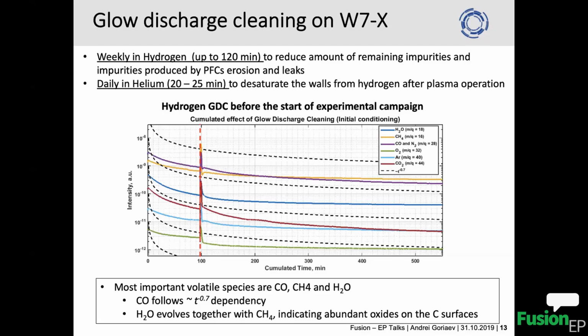Then you have some hydrogen accumulation, some other dust accumulation in your wall. Everything which comes from air is on your wall. So you close your vacuum vessel, you pump it down, and you still have some impurities on the surface or in the bulk of your plasma-facing components. To speed up the outgassing you apply baking, but baking is not really effective. Either you have to bake for a really long time to get rid of most of the impurities, or you have to apply something more powerful, which in this case is glow discharge cleaning.